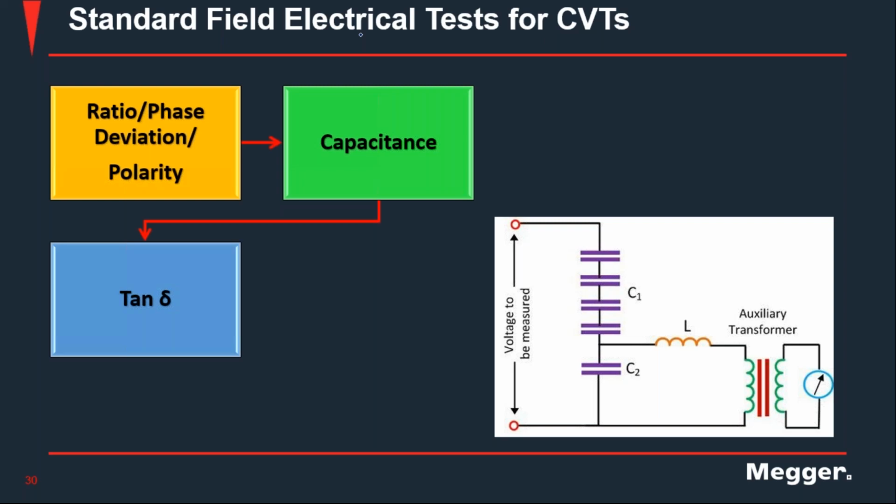The criteria to analyze these results are a little bit different than the other aspects of these measurements we do for instrument transformers. We do not have a hard limit or number that we're looking at, depending on the type of CT. This has to do more with the application of that particular instrument transformer. Where is it installed? What is the purpose of that instrument transformer? Again, there is no exact number or limit in terms of percentage that you're looking at.